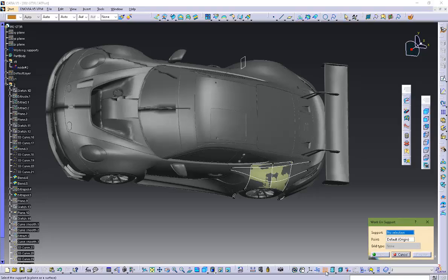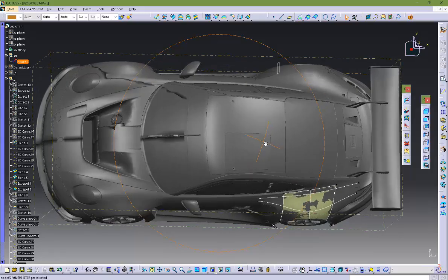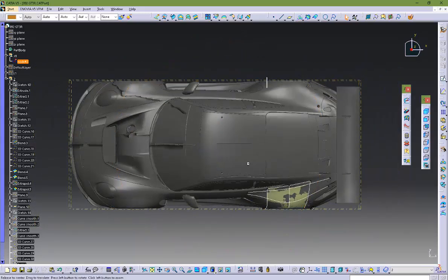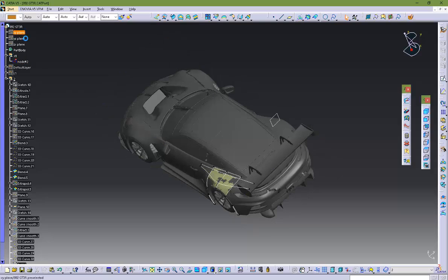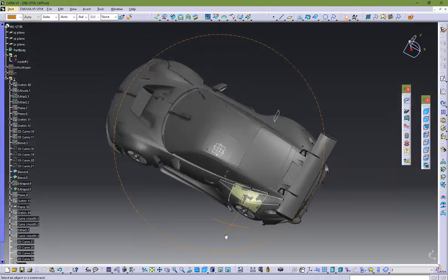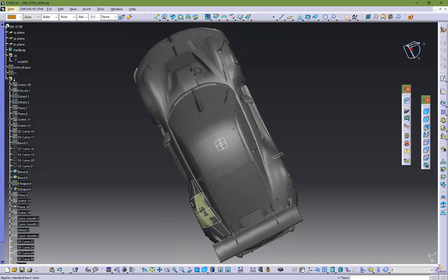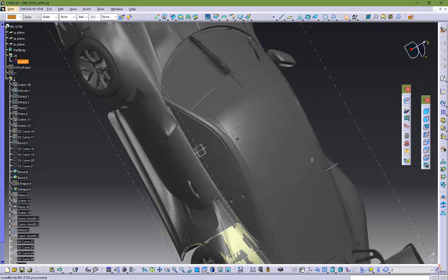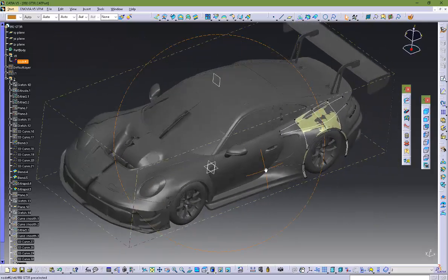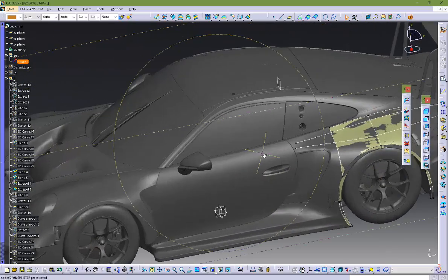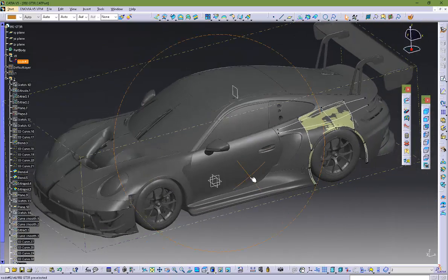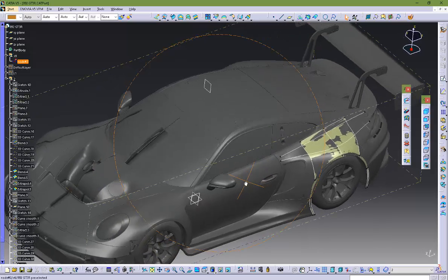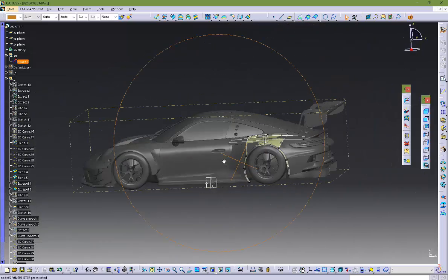The positioning is most important, and I have positioned it exactly at the zero and with LH/RH symmetry. I mostly position and scale it in Alias, and there is an advantage in Alias: you can save it directly as a CATPart file. So finally, I got a direct CATPart file with this STL data. There are other ways to import into CATIA also, and position and scale it directly. So this model is already scaled and positioned perfectly.